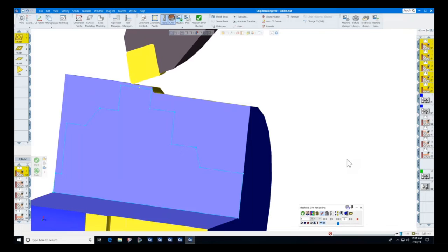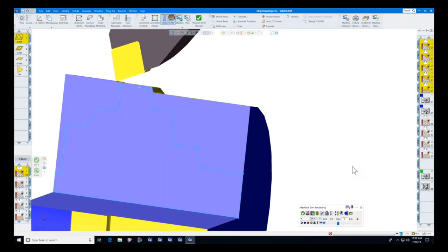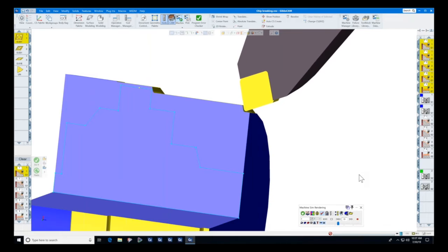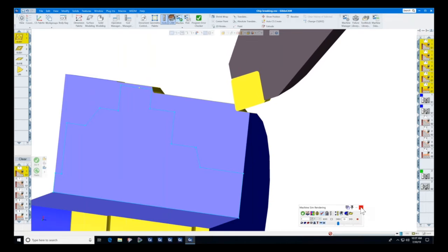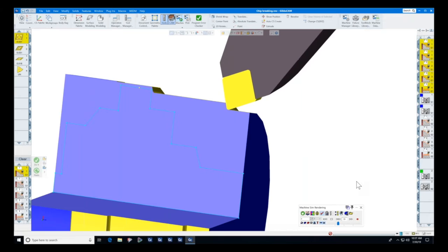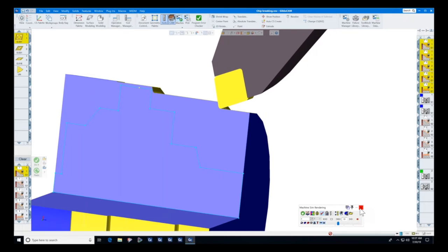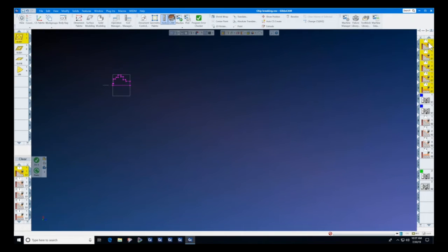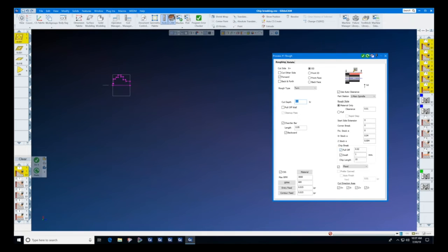We're doing everything that we can do to help you break that chip, and also do it at a fast enough rate to where you don't lose production. And the upside is that you don't have to keep opening the door and get rid of the bird's nest. So let's look at what we did to make that happen. Pull off, dwell, and chip length.